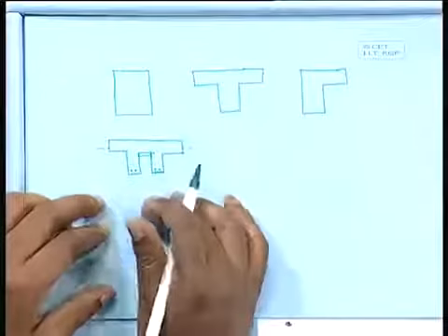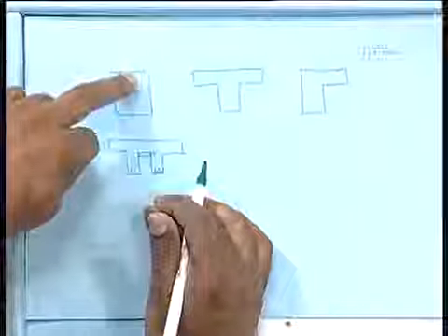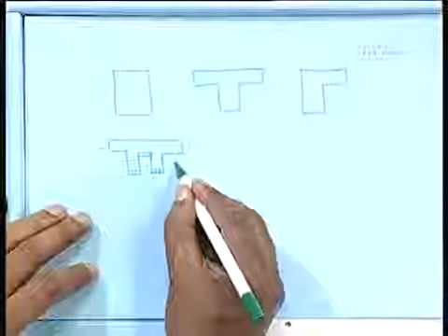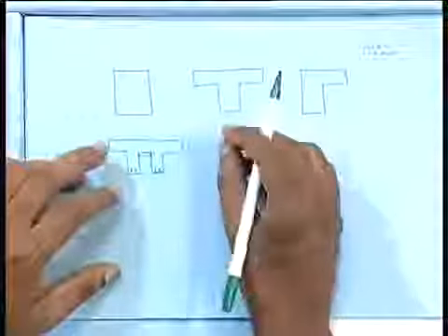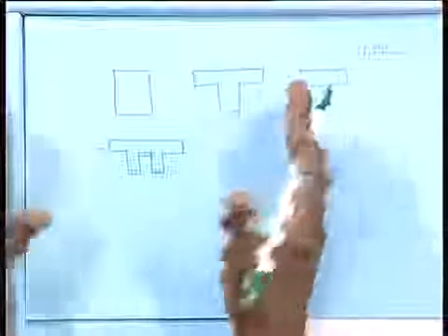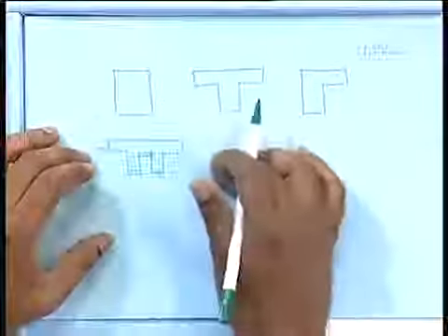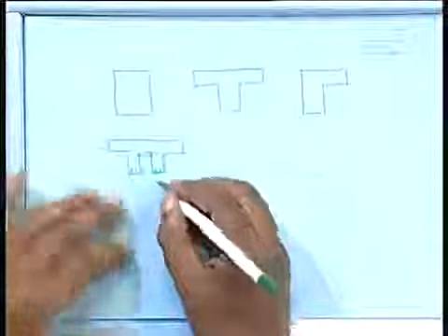So, this is nothing but a T-beam, or you can come back to that. Otherwise, if the neutral axis falls in the other option, then you have to do that calculation. So, in this case, it is always preferable that I keep the neutral axis within the limit. That is one tricky solution, so our calculation and other things will be easy. So, this is one problem.